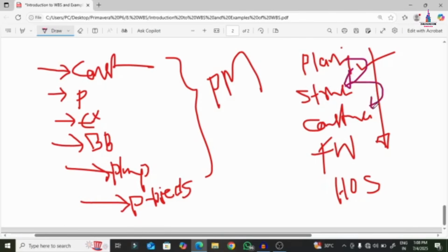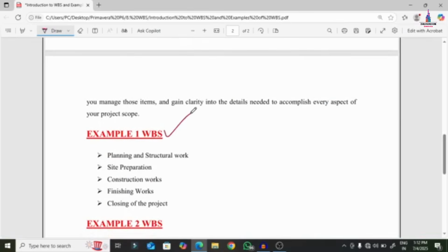In the construction work, we have different individual tasks like excavation work, site marking, excavation, as well as columns construction, footing construction, plinth beam construction, walls construction. Again, it will consist of plastering and bar bending, slab construction, curing, as well as the finishing of the project, and plumbing work and painting work, etc. will come under this WBS. Whatever the works which are generally carried out in a step-by-step process, we will call it WBS, work breakdown structure.